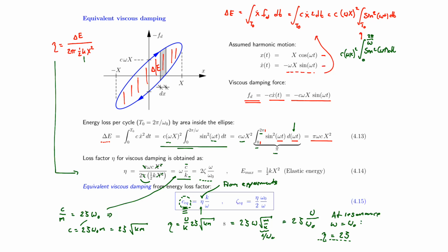And it turns out you should take your loss factor, that's the one here, and multiply it with the stiffness of the structure and the natural angular frequency by which you will then oscillate your structure. And in terms of the equivalent viscous damping ratio, if that is of interest, you should take half the loss factor and then the frequency ratio between the natural angular frequency of your structure and the applied angular frequency of your assumed harmonic motion.